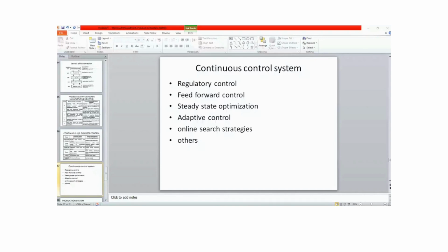But in the case of the feedback control system, whatever input we have given, the output will come. With respect to the given input, if there is any output difference, the feedback signal sends signals to the input to make the necessary changes. But here it is not like that. In a feed forward system, it makes corrective actions beforehand, considering that a disturbance may or may not occur, and based on that it carries out the feed forward signals in order to get a proper output.